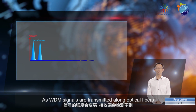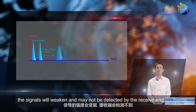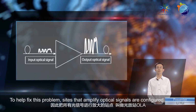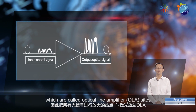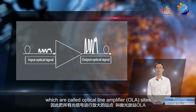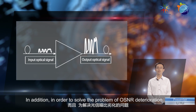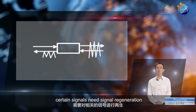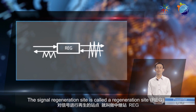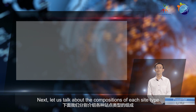As WDM signals are transmitted along optical fibers, the signals will weaken and may not be detected by the receive end. To help fix this problem, sites that amplify optical signals are configured, which are called optical line amplifier sites. In addition, in order to solve the problem of OSNR deterioration, certain signals need signal regeneration. The signal regeneration site is called a regeneration site. Next, let's talk about the compositions of each site type.